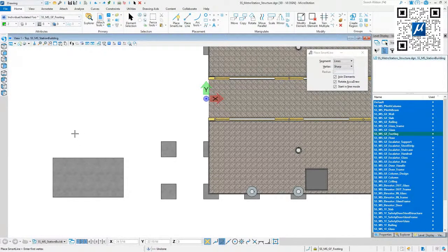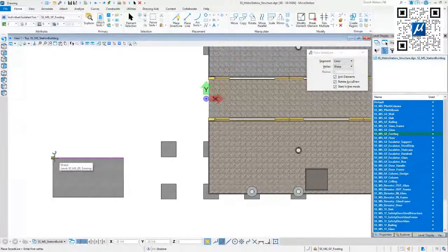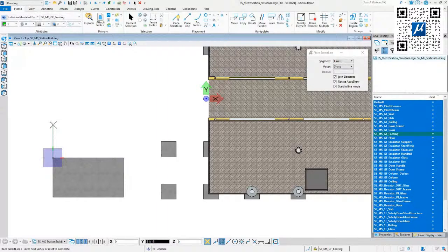So one of these Accu features in MicroStation is AccuSnap. AccuSnap is that you get close to an element, to a vertex of an element, and then you can see this little yellow X coming up. That's a snap feature. So I can go here and then left click to accept, and I start drawing from here. And I'm sure that this point will be exactly at the right location. It will connect to the existing element.